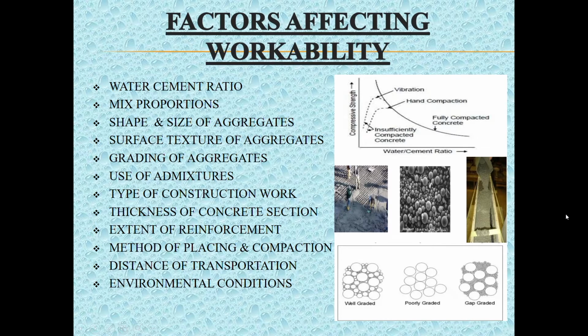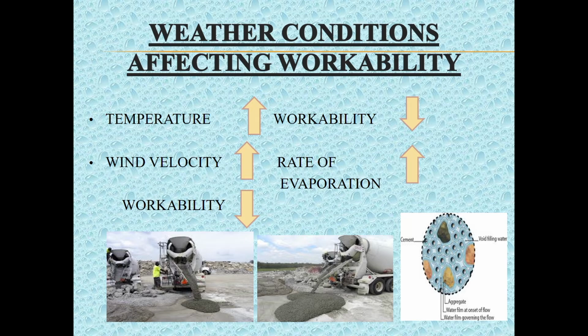Use of fine pozzolanic materials also has a better lubricating effect and more workability. Weather conditions also influence the workability of concrete. If temperature is high, evaporation increases, thus workability decreases. If wind is moving with greater velocity, the rate of evaporation also increases, reducing the amount of water required for lubrication, which ultimately reduces workability.